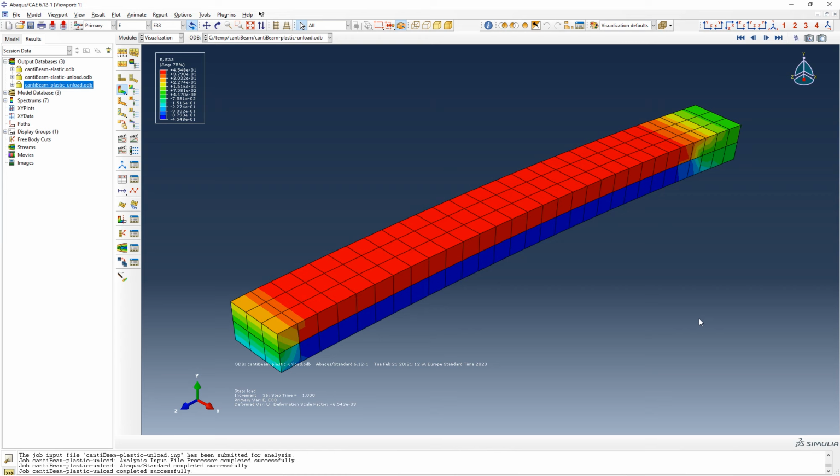You can define a more detailed material model based on realistic stress strain curves for steel, and you will see better and better results, or the results that will match your hypothesis, or that will match your imagination.